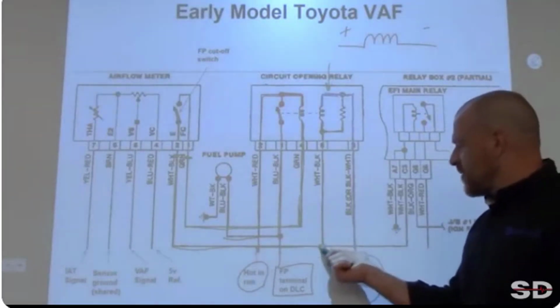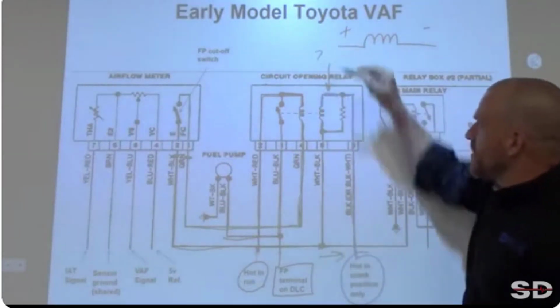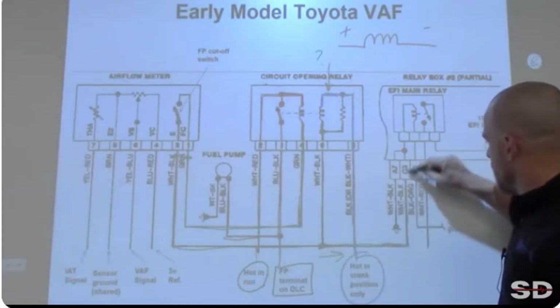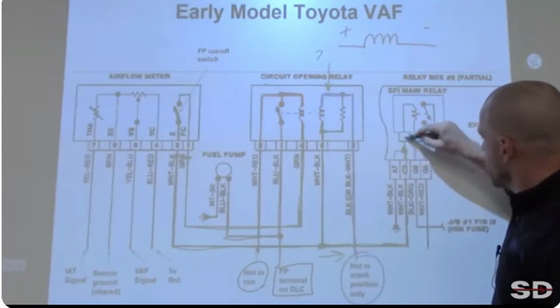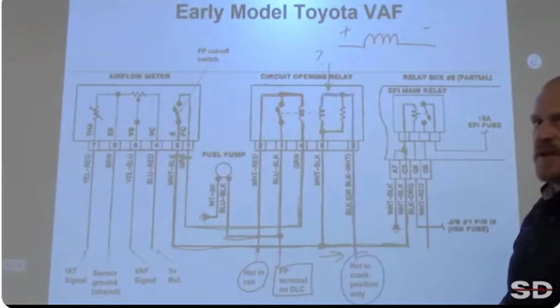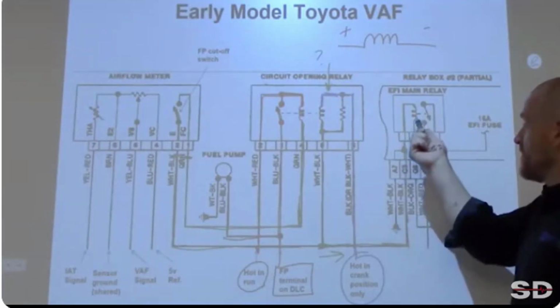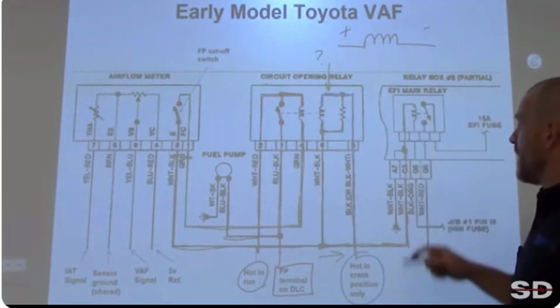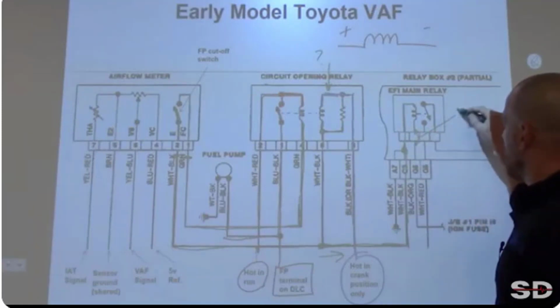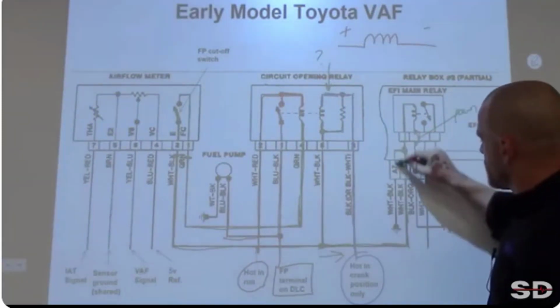All right, so let's follow the rest of it. If you had a question mark here, follow the rest of it. Let's follow this green circuit. Where's it going? Up to here, another splice. Up to this coil. Should I draw through or stop? Stop. Gotta stop. What's the other side have to be? This is a ground I'm mapping out. This side of this circuit is going to be a power. But here's your ground right here.